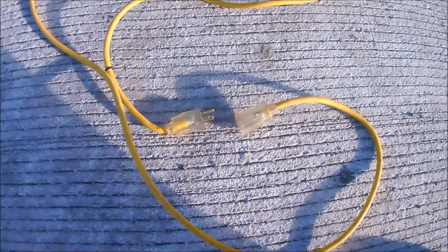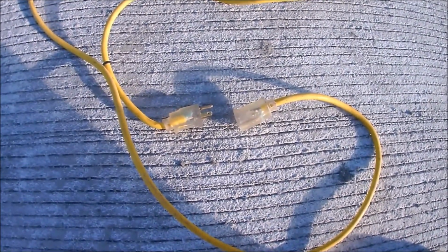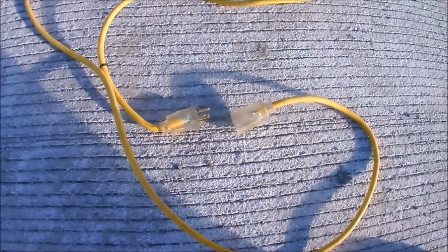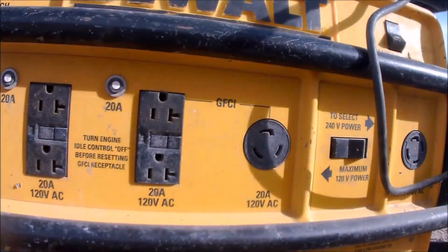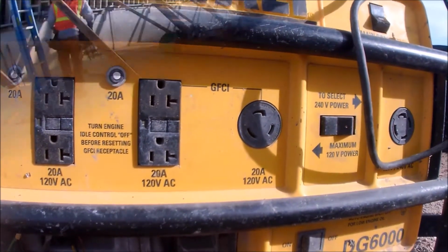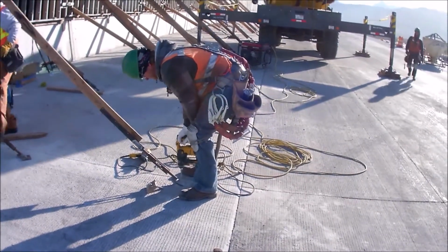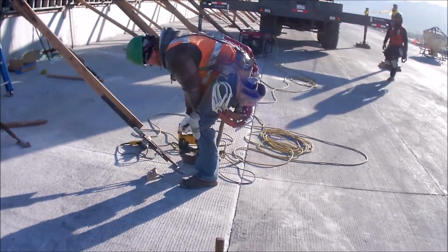Power tools require the following. The power cord must be intact. The tool must either be grounded or double insulated. Any guards included with the tool from the manufacturer are to be maintained and in place. Half-inch or larger drills require 2 handles.